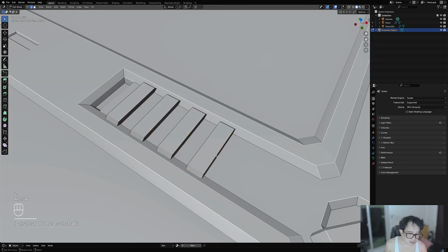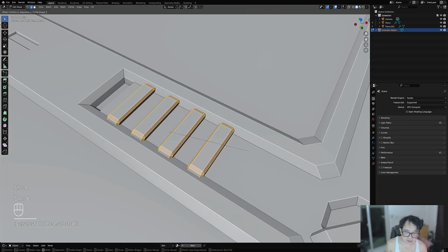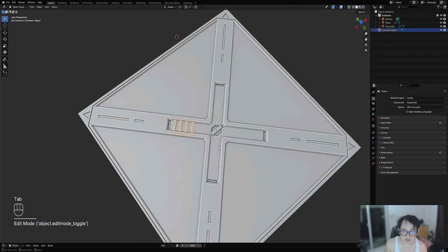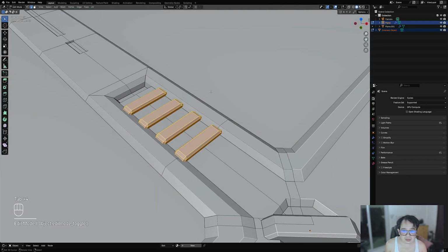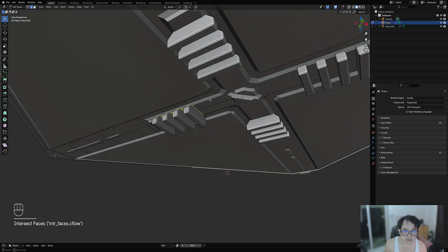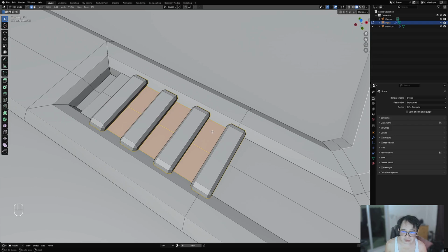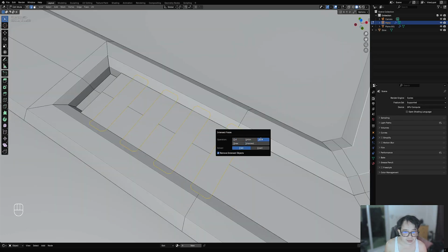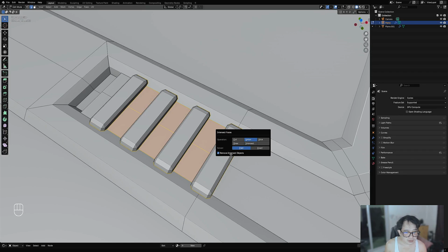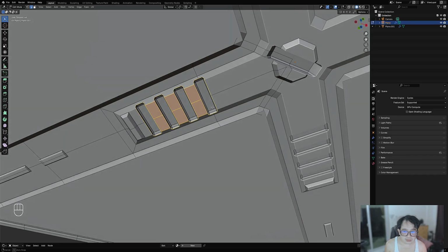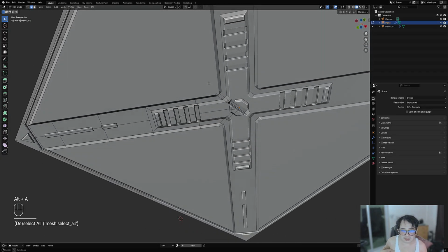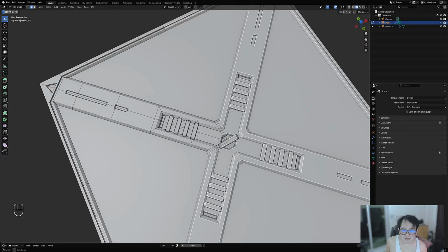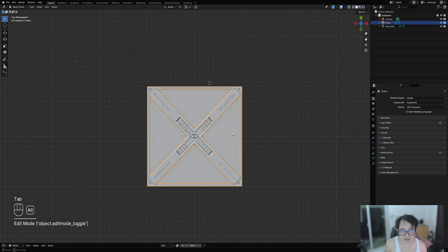But first, we need to bevel, and then we can use the union operation, but in this case, it's straight cut, intersect, slice, union, intersect objects, exact. There we go, exact, not fast. So we have that detail.